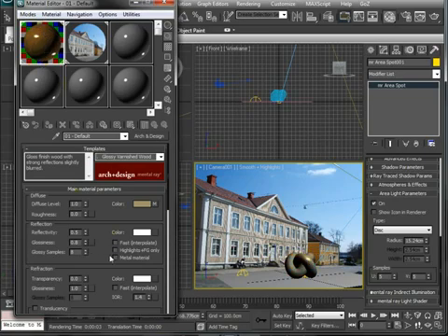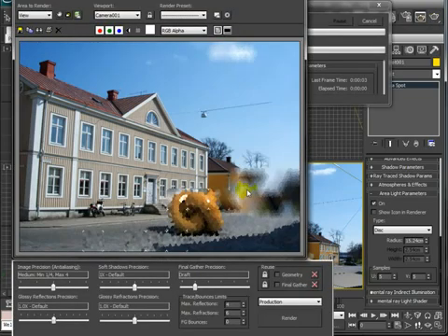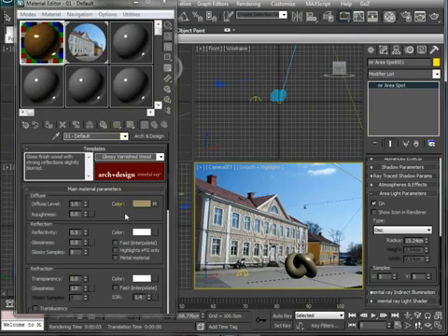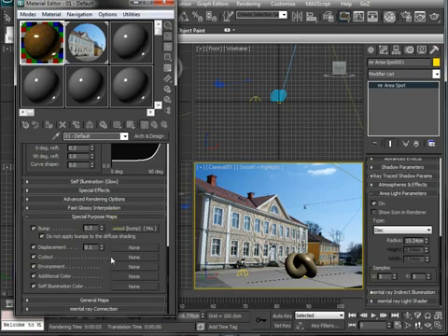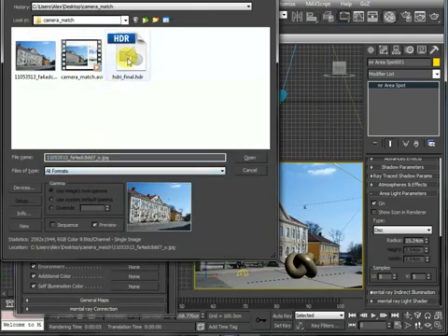And what I'm going to do is a quick render. You can see that it will kind of look see-through. Look, you can see the building behind it. That's because this is a reflective material, and it's trying to reflect this environment, and the environment is a 2D image that won't wrap around, so it ends up looking transparent. To correct that, in your material editor, you want to introduce a material to the environment tab here in the special purposes maps. Now I'm going to introduce a bitmap, and I'm going to introduce it with this HDRI final image.